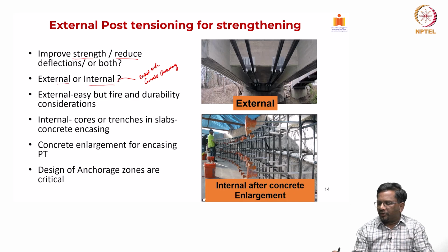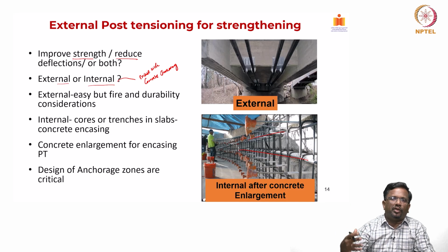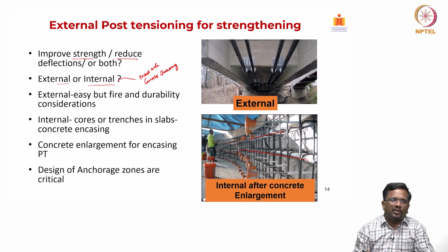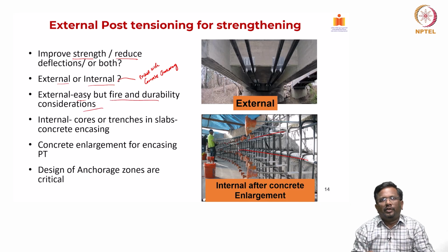right. That means the system here, you have this PT cable that is running. And because I am adding an external concrete jacketing as well, now the PT cable will be embedded within the concrete. So, it becomes an internal system, as part of the original structural system. External is easy, but again fire and durability considerations are there. So, if you want to improve the fire resistance, then I have to go for some kind of fireproofing that we need to do.